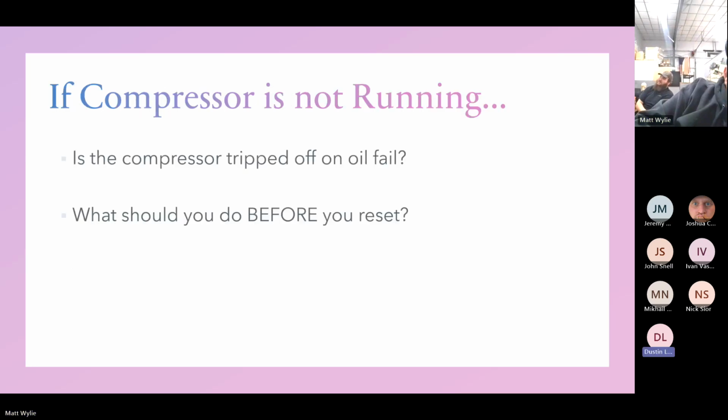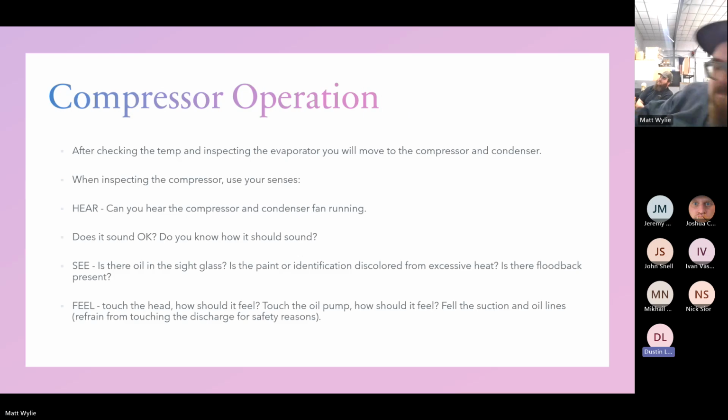I like that you mentioned the 3-phase power and the compressors running backwards. It's a good reminder for everyone that if you're changing a 3-phase motor or a compressor, you always have to verify rotation. Not even just compressors, but blower motors on a 3-phase RTU. You could have a brand new RTU, and everything's going to work fine, right? It's going to work right out of the gate, hopefully, and you're just going to land 3 wires of power to it and not think twice about it.